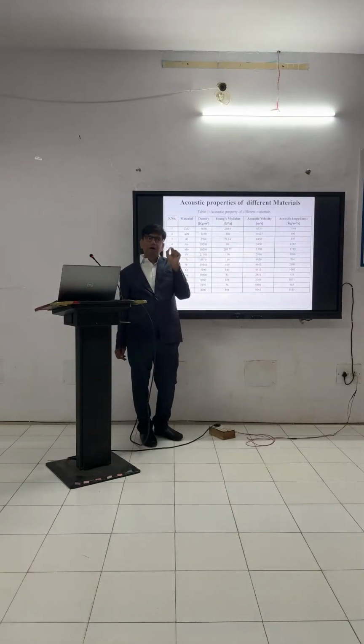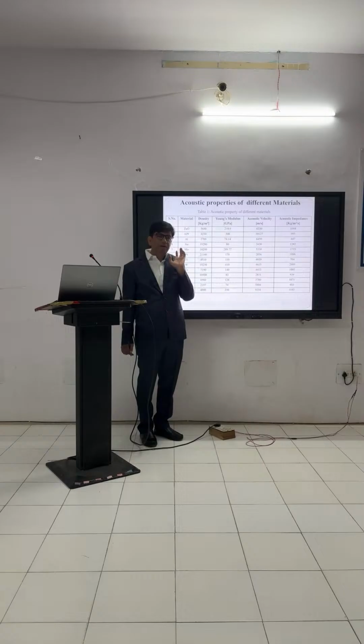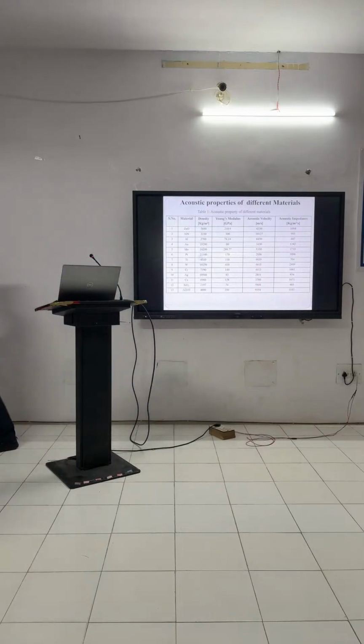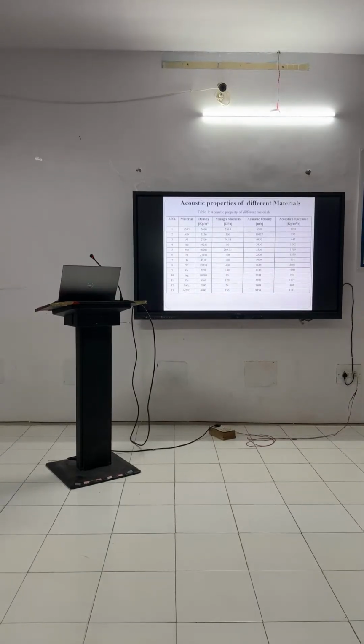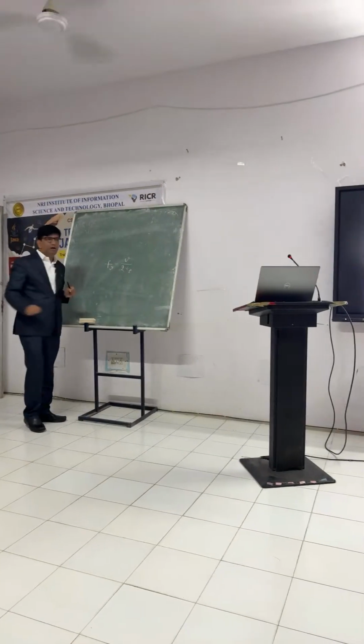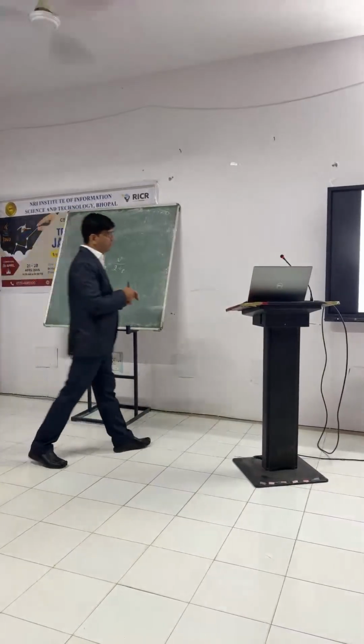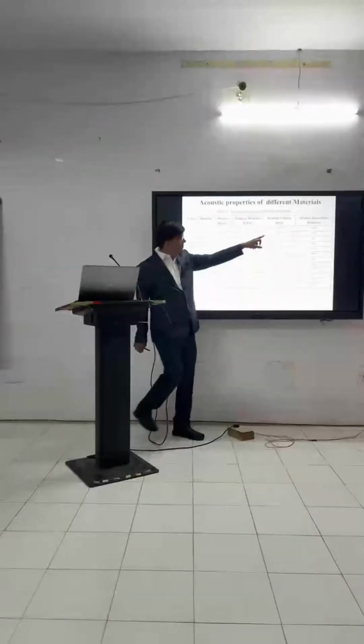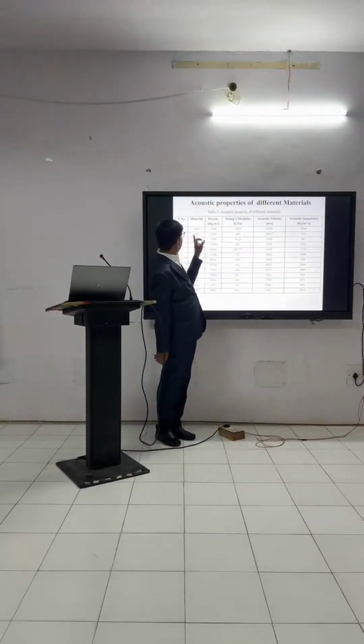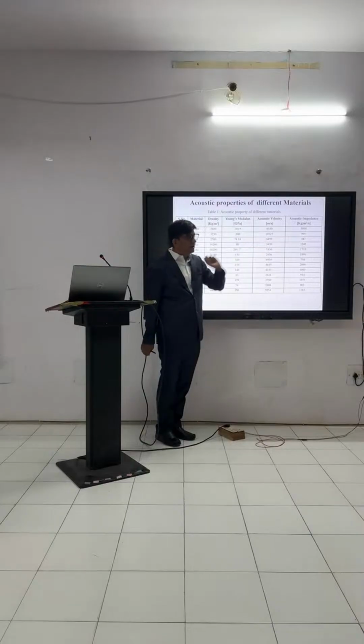So if I am thinking about my piezoelectric layer, what I am looking for is my frequency. So how do I decide my frequency? I have two parameters. What are these two parameters? See, I have this resonant frequency that depends on v divided by twice of d. So this v is fixed for any piezoelectric material. For example, ZnO. What is my acoustic velocity? 6330. If I select aluminum nitride, that is 10,127.